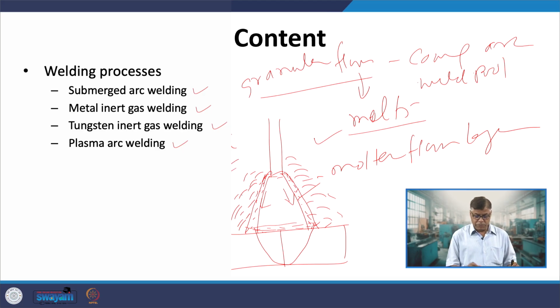So, these oxides when decomposed they produce a lot of oxygen, and therefore, weld metal produced by the submerged arc welding usually contains a very high percentage of oxygen. So, it is very rich in terms of the oxygen, and that will be leading to various oxides in the weld pool.